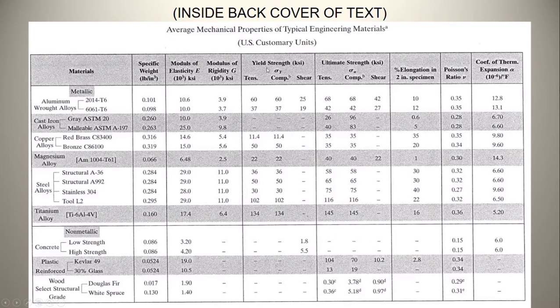In the case of yield strength, it's directly given in KSI. There is no header, but it is still KSI, not PSI. For example, if you see the A36 steel alloy, a very common steel alloy, its ultimate strength is 58 KSI and its yield strength is 36 KSI.